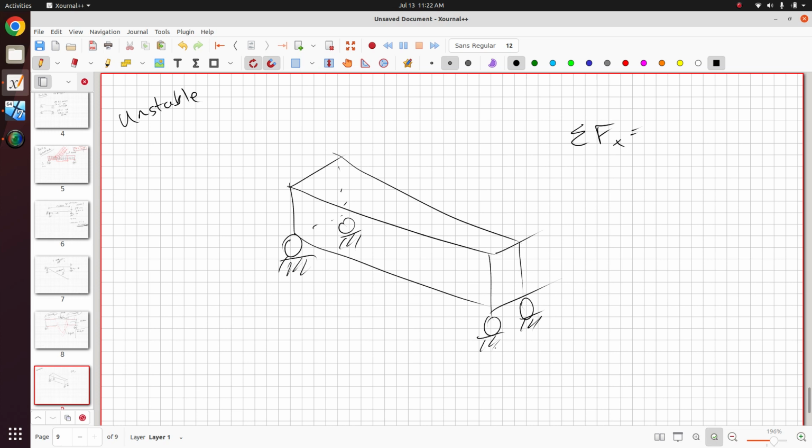First, define your boundary conditions. Now, this is a trick that one of my professors taught me a long time ago. You apply 3 fictitious loads on your structure. So pick a point, preferably somewhere away from the boundary conditions. Here, maybe at the top, we'll pick this point, and then we're going to apply a load. Maybe this is the X, this is the Y, and this is the Z.